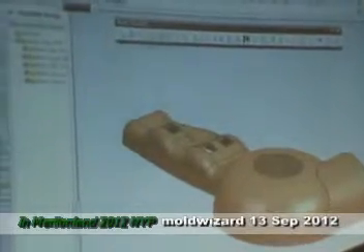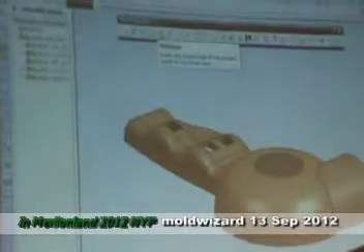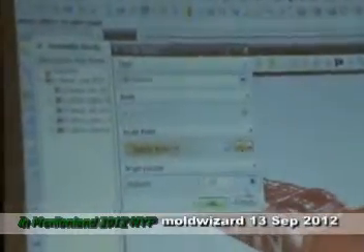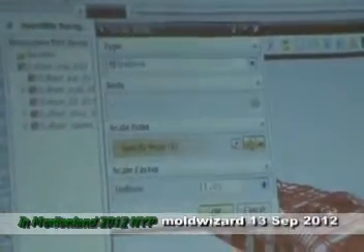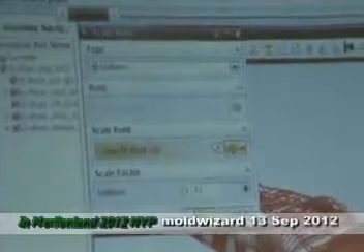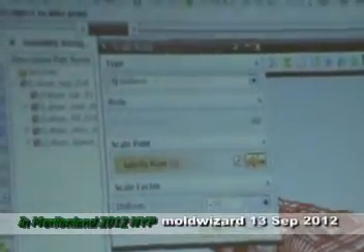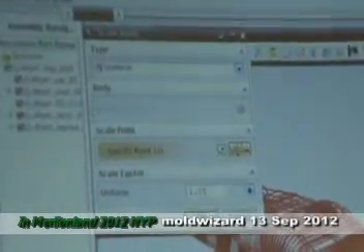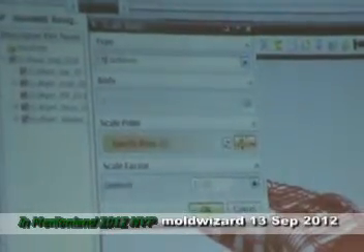So now we go to this shrinkage. You want to change? Just now I keyed in 1.02, remember? So now, if I want to change, you can change. I change to 1.01 now. So in a later part, for example, if you want to change the shrinkage even after cutting, you still can come back to this place and change it.